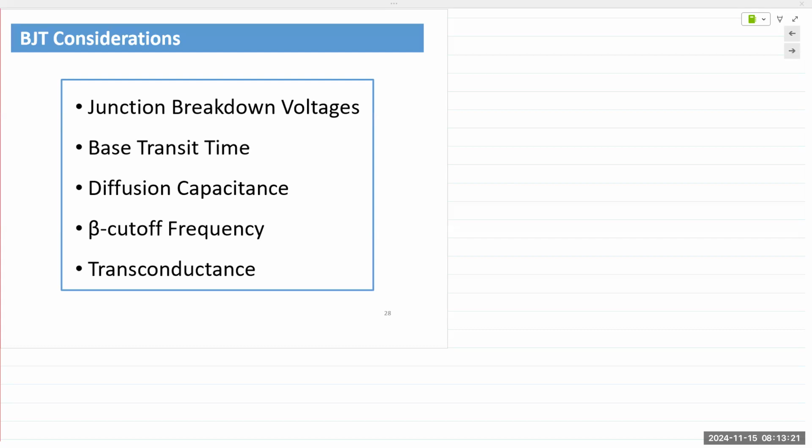Okay, so a transistor, a BJT, is made of two back-to-back PN junctions. And so it behaves like any other PN junction diode, whether it's a PNP transistor or an NPN transistor. We are either forward biasing or reverse biasing these junctions. And so like any other PN junction, these junctions also break down. If you reverse bias any of these junctions, they will break down similar to a PN junction diode. And we saw this in the lab, where we can use this characteristic to determine which terminal is the emitter and which is the collector.